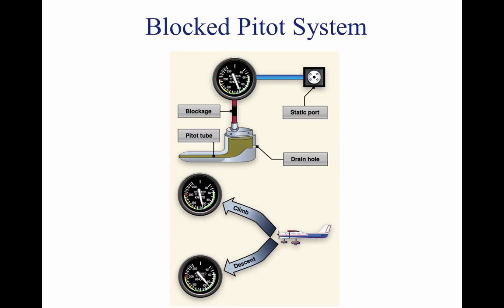Because airspeed indications rely upon both static and dynamic pressure together, the blockage of either of these systems affects the ASI reading. Remember that the ASI has a diaphragm in which dynamic air pressure is entered. Behind this diaphragm is a reference pressure called static pressure that comes from the static ports. The diaphragm pressurizes against this static pressure and as a result changes the airspeed indication via levers and indicators